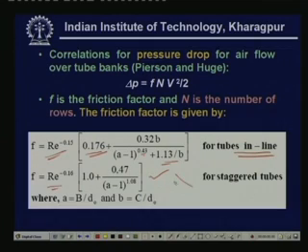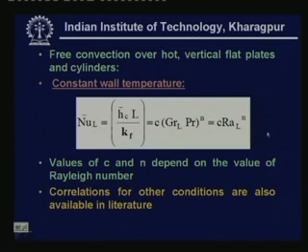And in this friction factor expression, the constants A and B are defined in terms of the tube to tube spacing capital B and the outer diameter of the tube D naught, and row to row spacing C. Okay. So, if you know these details, we can find out A and B, then from that we can find out the friction factor. Okay. Now, whatever expressions we have shown so far hold good for forced convection type air cooled condensers. Okay. So, in fact, in the last lecture I have also mentioned natural convection type condensers.